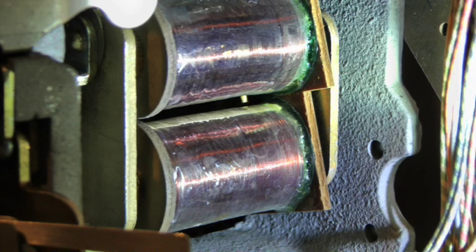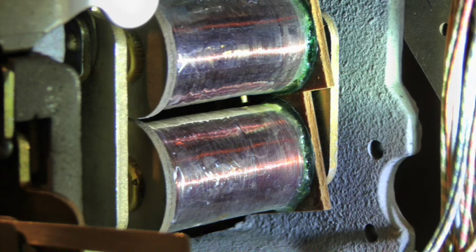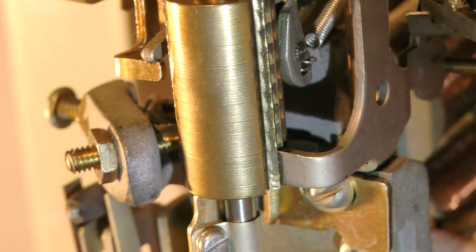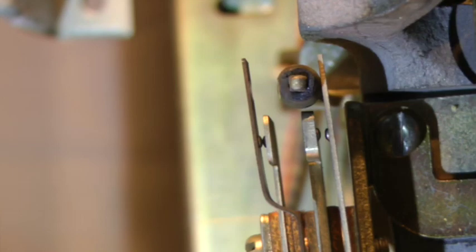The release of the C relay de-energizes the rotary magnet, and so the rotary armature releases. And the rotary pawl disengages from the rotary ratchet. The rotary interrupter arm releases, reclosing break contacts 1 and 2 and opening make contacts 3 and 4.